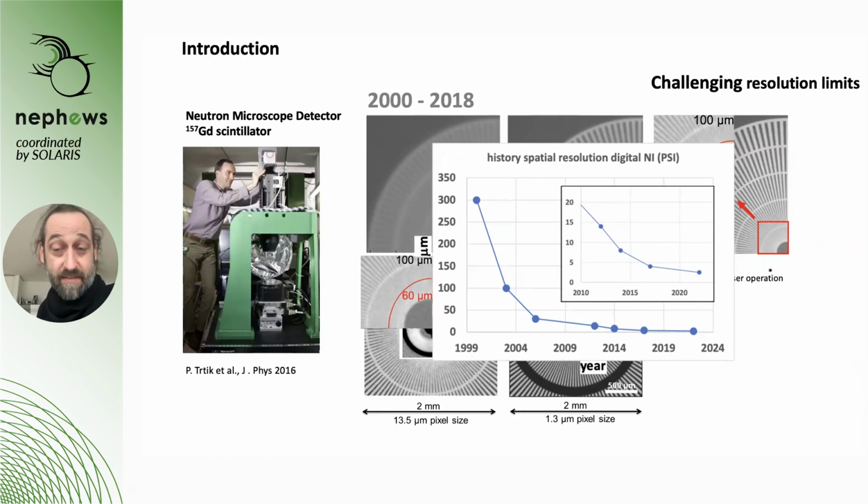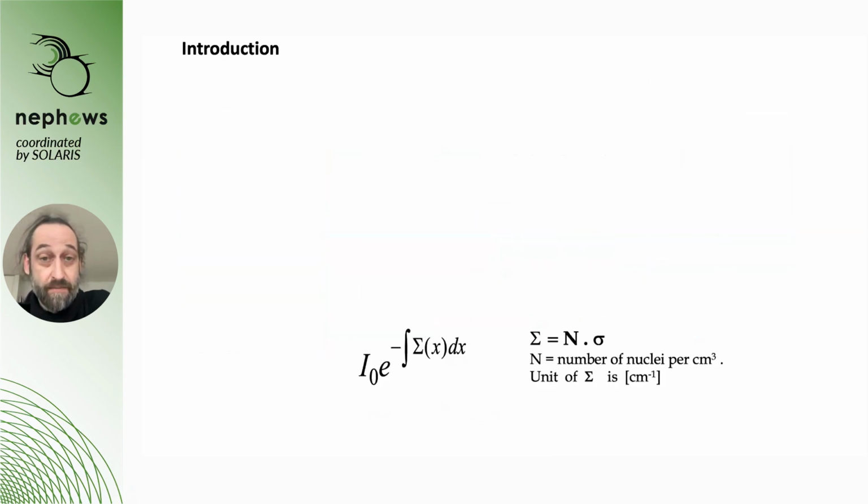But what you have to see is that if we go to such high resolution, which is similar to what you typically have with X-rays, then our samples also become very small, and that means we only have samples of a few millimeters. And then some advantages of neutron imaging, of course, go away, because when samples are very small, you can also penetrate with X-rays and so on, and you have hard times already to get contrast. But still, we're pushing further and see what we can do.